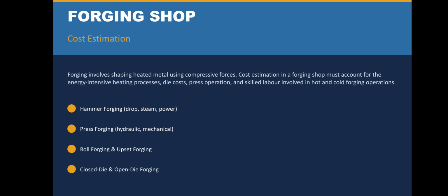We can find out the losses using different formulas, to find out the losses included in the forging operations, such as shear loss, tongue hold loss, scale loss, flash loss, sprue loss, etc. Mainly 5 losses are included.